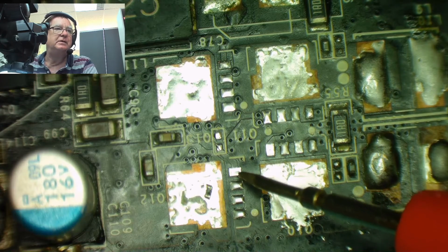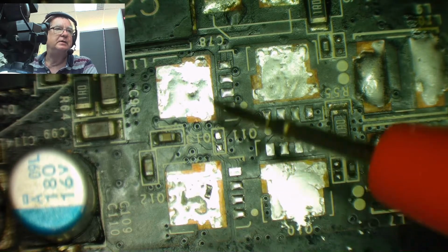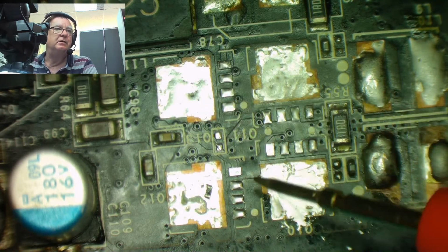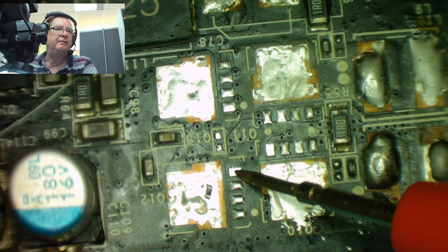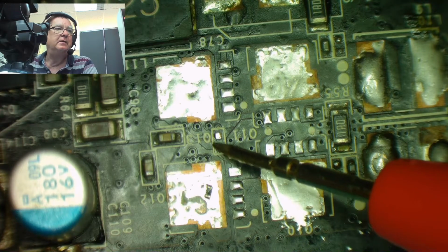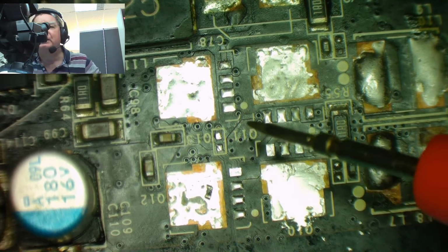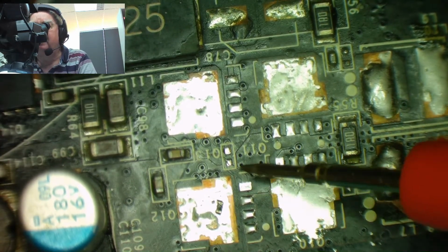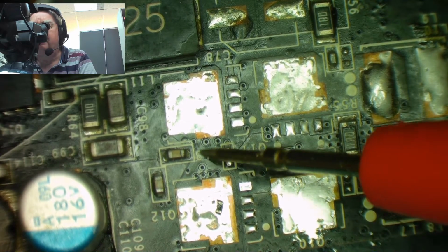Looking at it, this is the high side MOSFET. This is the other high side MOSFET. So the two channels are identical, just phase 1 and phase 2. And you can see that from this pad here goes to here. So this is where the resistor is. One end's connecting to the gate of this phase, and then the other end appears to go down through the board here